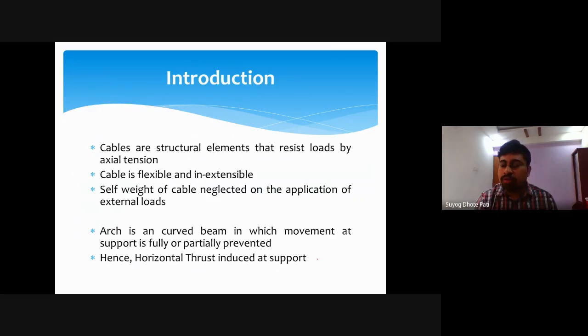During analysis we consider that the cable is flexible and inextensible. Inextensible means that whatever length is considered for that particular cable, whether 3 meters, 4 meters, 5 meters or 10 meters, that length will be the same after application of load. Before and after application of load, there will be no change in length. That is what inextensible cable means. And the cable is considered a flexible member, not a rigid member.